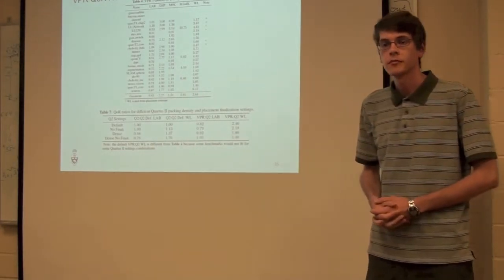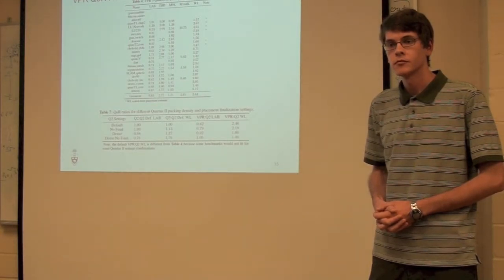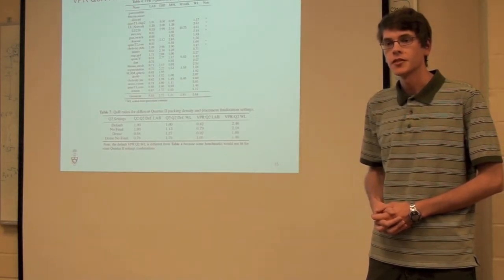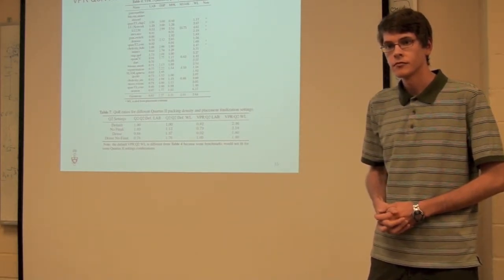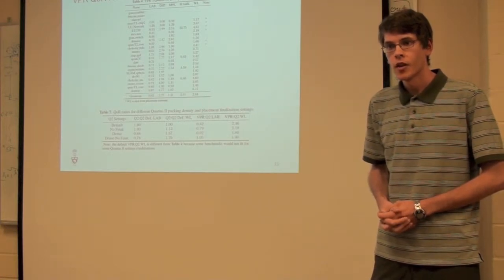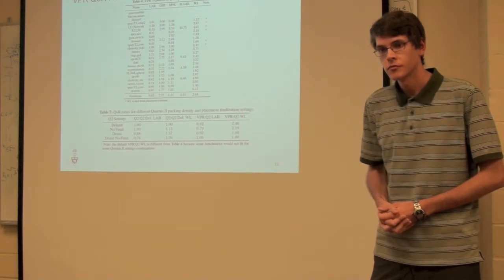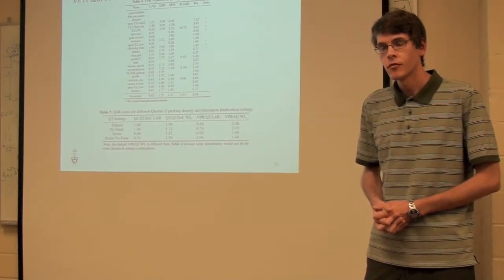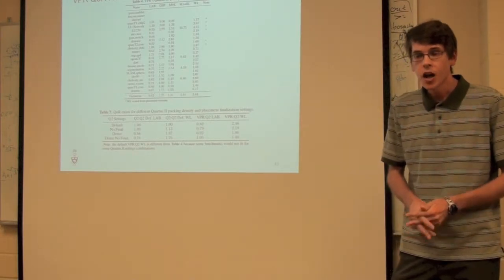Yep. Follow up on the whole packing density wire length discussion. You said that none of this is timing driven right now, right? Yes. So this might not be true, but the only reason we care about wire length is mostly because we want shorter wires to have better timing. So if you had timing driven everything, wouldn't that naturally want to choose a configuration that minimizes wire length as opposed to packs things together just because it's cool?